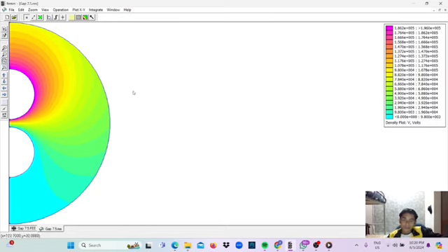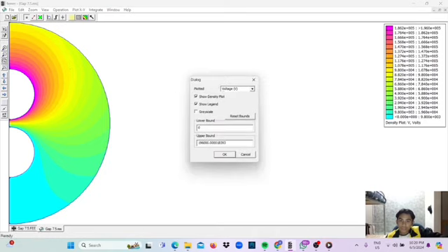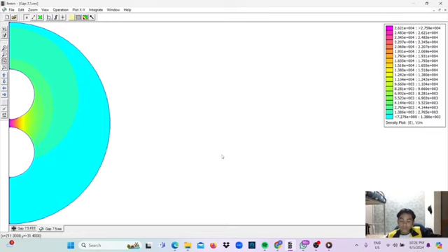After that, we can see the electric field intensity in the electrode. Now next we need to see the value of the electric field intensity in the 7.5 cm gap. Let's choose the field intensity. And then we can see the lower bound is 7.27 and the upper bound is 27585. Next we need to see where the highest electric field intensity is.